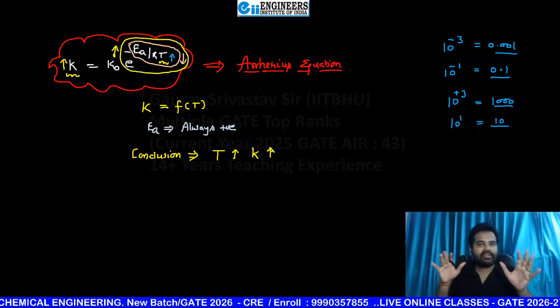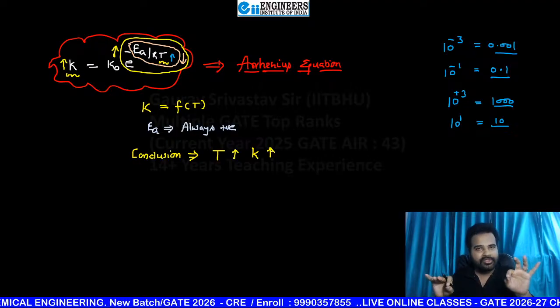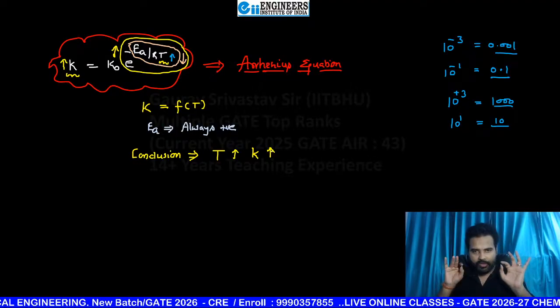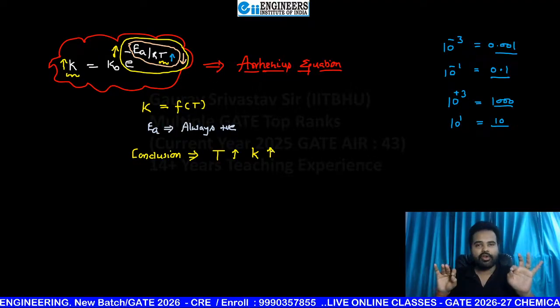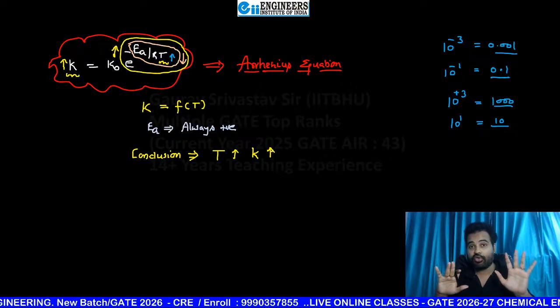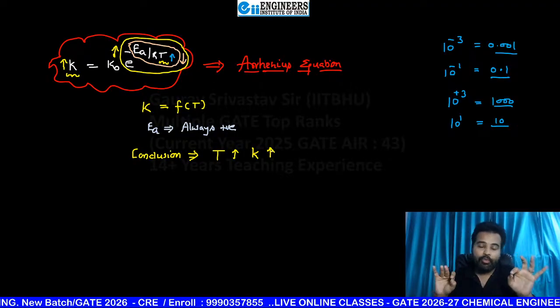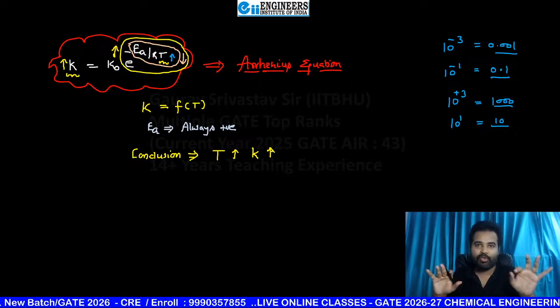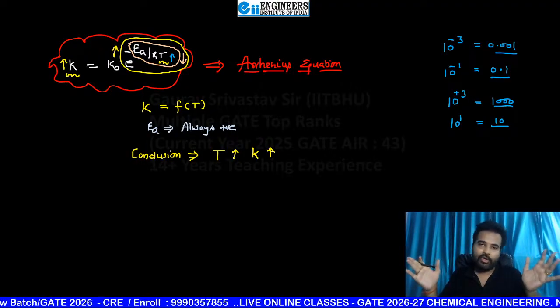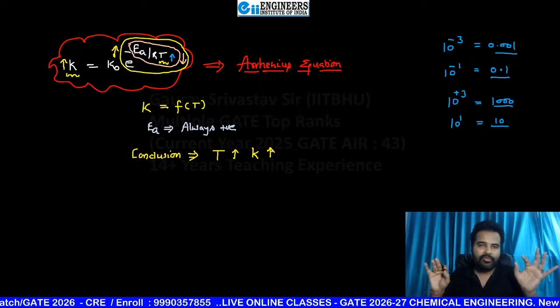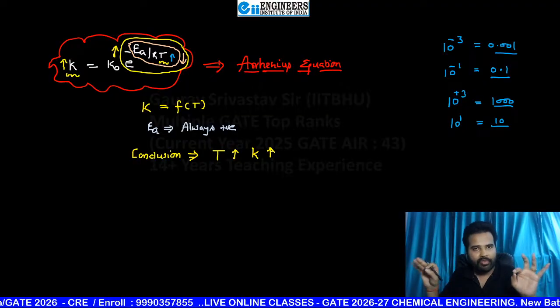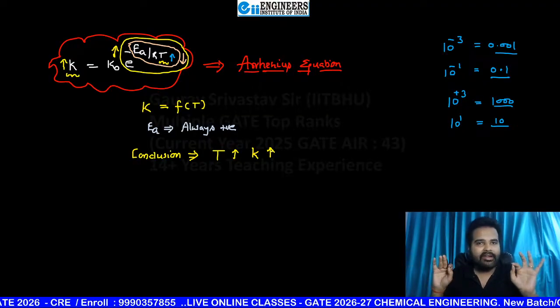That's why in general, if it is an irreversible reaction, every time we want high temperature because high temperature is favorable, but make sure the temperature is below the melting point of your chamber or container, or the dissociation temperature of either reactant or product. So the reaction should happen at high temperature.